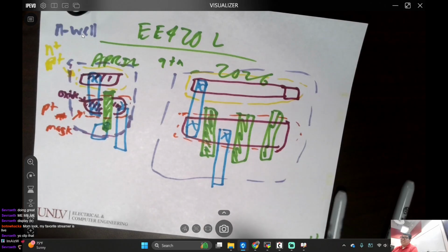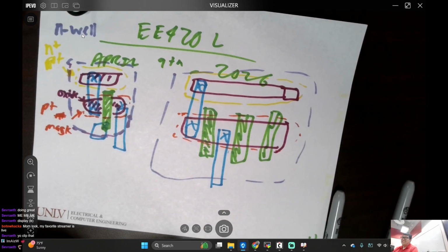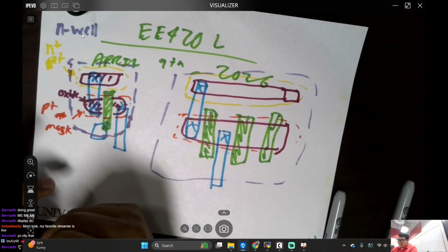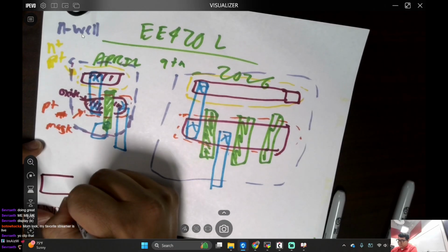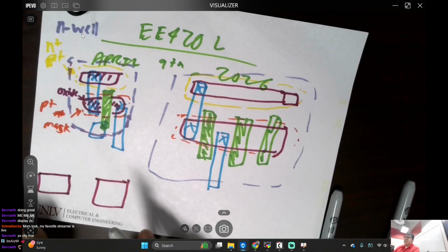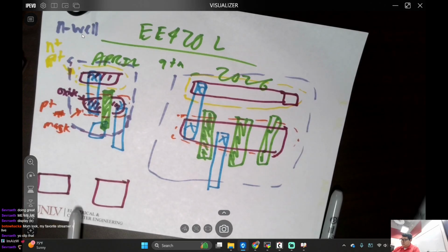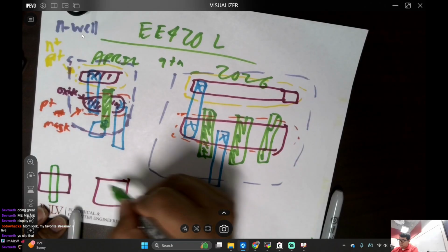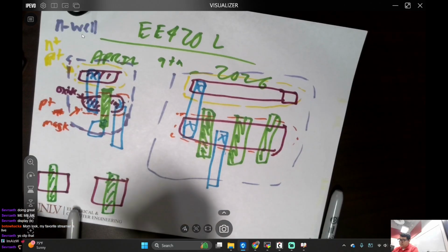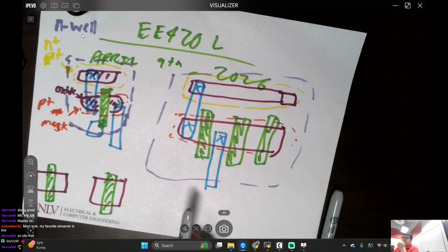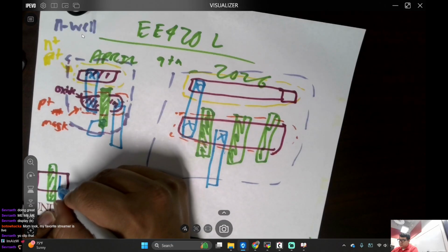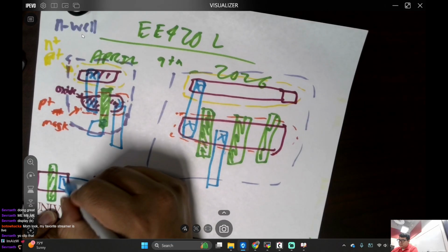I think we went over this like the third or fourth week of school, right? And yeah, that's what my question was about. If you have the multiple gates, it makes multiple transistors, right? Yeah, multiple transistors, yes. Because I tried doing that for my 421 project for the Schmitt trigger. I had the two NMOSs of the schematic right next to each other, and I tried to use the multiple fingers to connect the drain of each one. But I got errors in my LVS, so I probably just did it wrong.